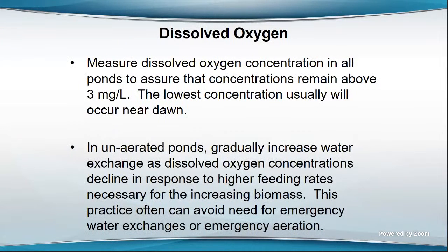Now, people should monitor dissolved oxygen in their ponds just to make sure they've got enough. And I don't know what the best concentration is, but I would certainly say you don't want the dissolved oxygen concentration to drop below 3 milligrams per liter.